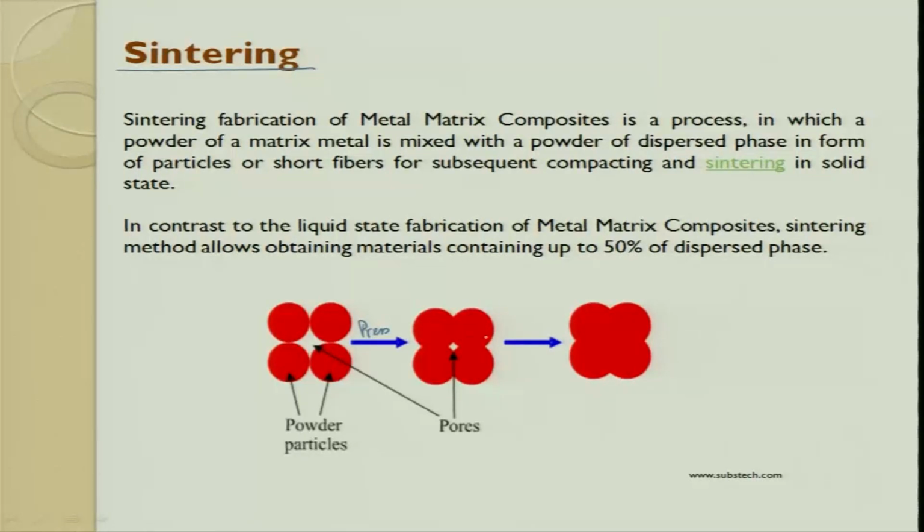Now, when it gets consolidated, you see there is a small space getting formed, and you still want to close this space. How can you close it? One, you can push in something there to close it, or you try to apply temperature. When you apply temperature, the consolidation happens in a big way. If you have a ceramic material of very high temperature, then naturally we go for an interface. We try to give a coating and then try to join it. If not, you have to think of a very high pressure, very high temperature, and then do it.